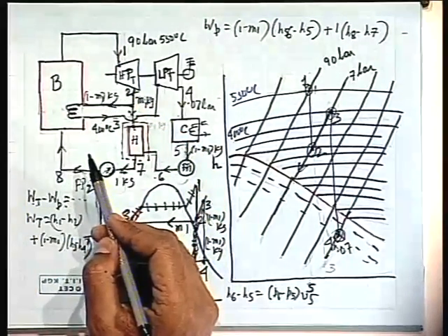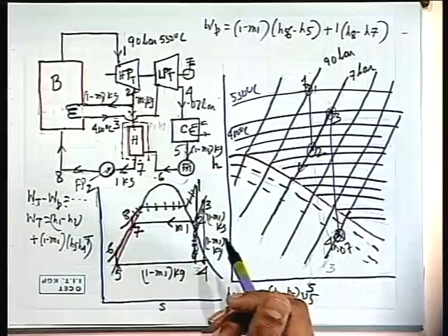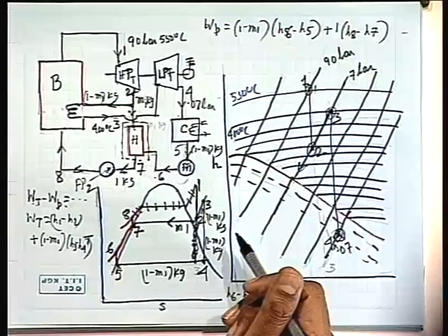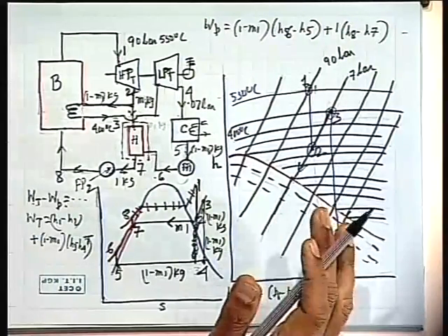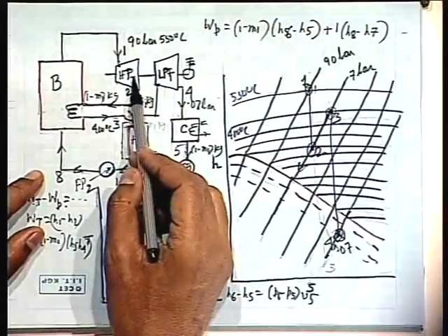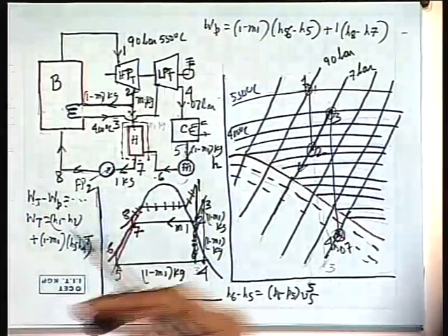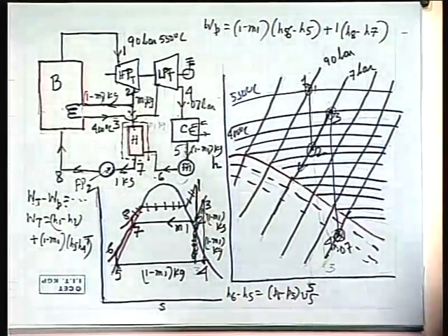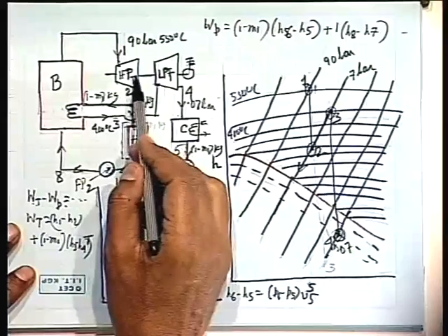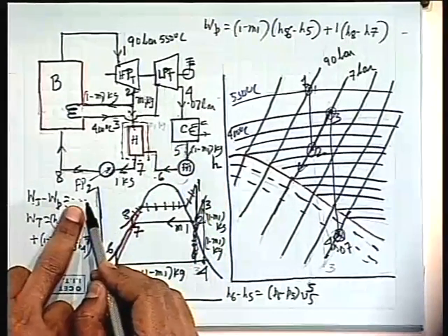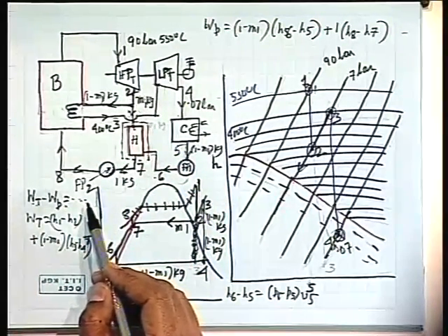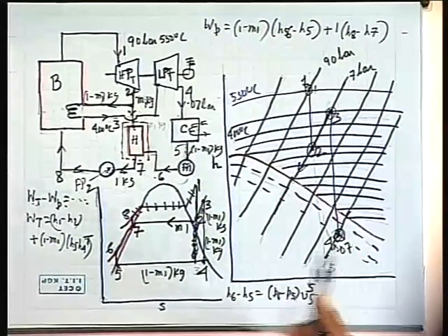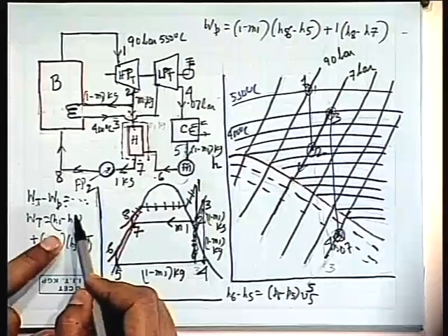The total power is 100 megawatt. Divided, did you get the steam flow rate? Now next is, what is the total pump work. So for 1 kg of HP turbine flow, this is the power. So just reverse, 100 megawatt, primary school level thing. You have to find out the steam flow rate to the HP turbine. For 1 kg of steam flow to the HP turbine, you get this power. For 100 megawatt power, steam flow rate. That means 100 divided by what you get.